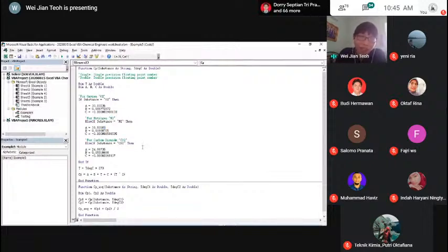Because sometimes, even when you have a process simulator like Aspen Plus or HYSYS, some things are better to just validate or verify with manual calculations, and we use VBA for this kind of manual calculation just to verify what the program is showing me. So we don't just blindly trust those programs like Aspen Plus and HYSYS. So I hope that answers your questions.